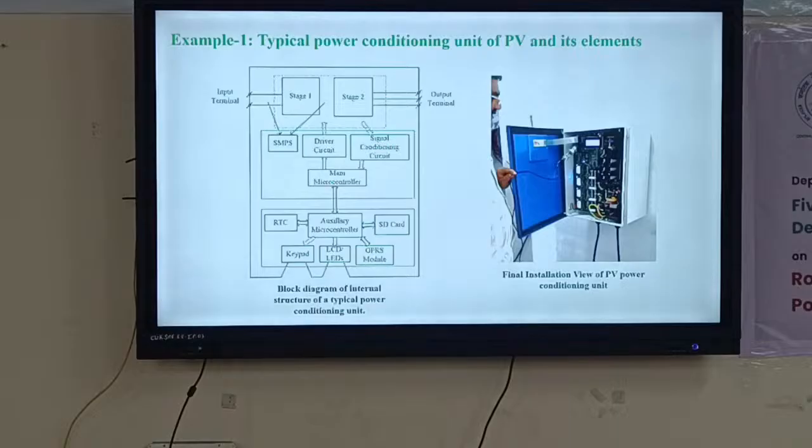So when you are doing research in developing a power converter, do not limit your research only to developing that DC-DC converter or AC-DC converter. Spend some time in developing the fancy LCD or LED display screen. Why? Because that will give you a means of testing your power converter. Say for example, what voltage you have at the output, what voltage you have at the input. You don't need additional multimeters to connect and increase the complexity in your prototyping.